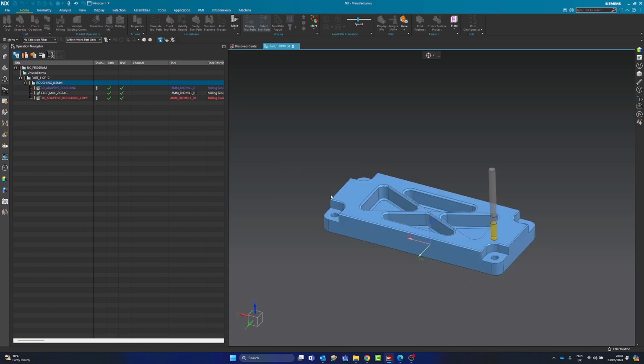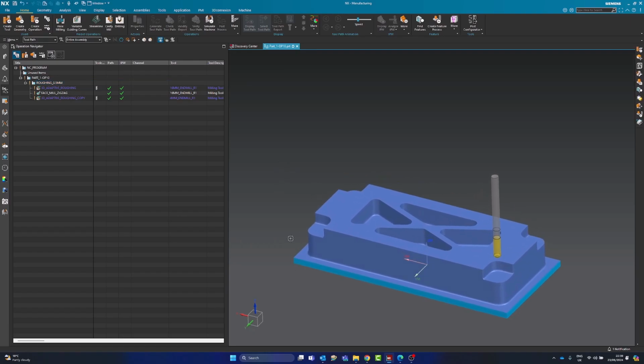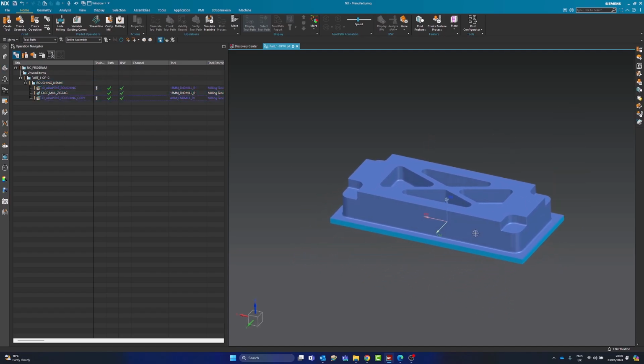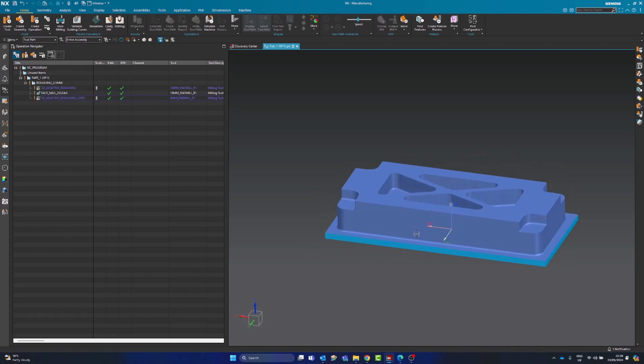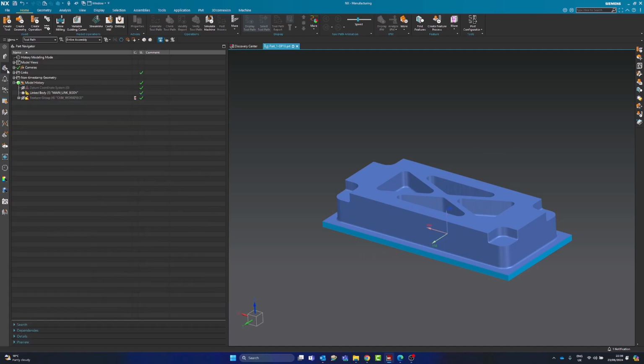Okay, I mean, that's not good. That's our first error of the evening. Okay, so you can see it's created the facet body on our screen here, which is because we analyzed it. It'll save an IPW, so where does that get put? If we go into the part navigator, you have this box here called non-timestamp geometry, and it's not in there, which it normally is. That's where I'd imagine IPWs to go. So let's just delete it from the screen.